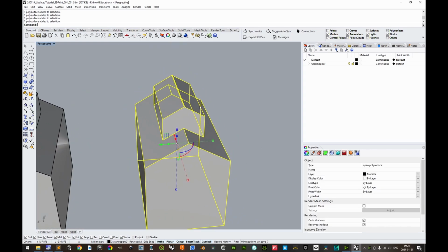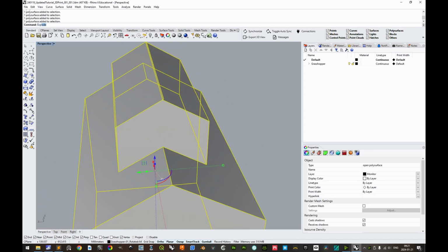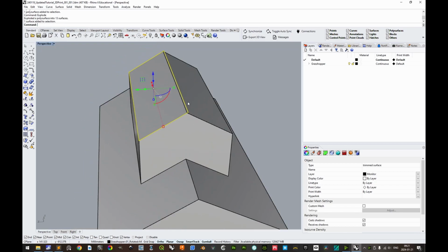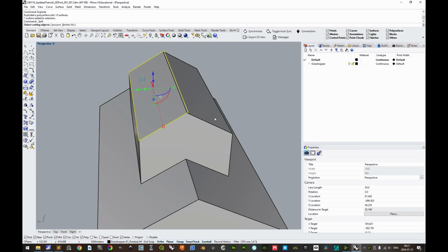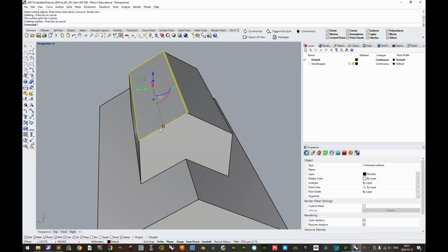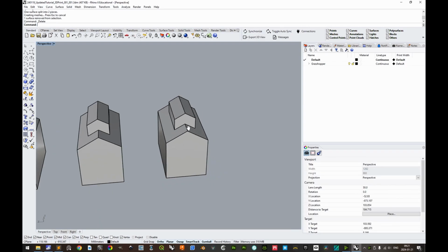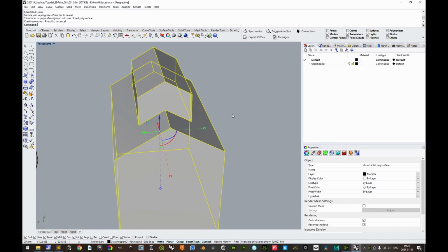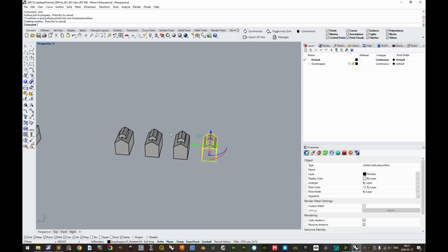In this case, it might be easiest to simply explode the object into individual surfaces, select the non-manifold surface, Ctrl-Shift-S to activate the splitting command, select the manifold surface which borders the non-manifold surface as the cutting object, space or enter to confirm, Ctrl-click the manifold portion of the non-manifold surface and delete the non-manifold portion. Now select everything again and Ctrl-J to join, and we have one closed polysurface. Very good. This can be 3D printed, along with the other 3 as well.